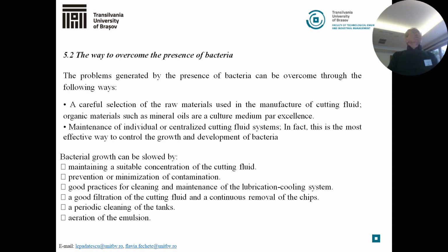Bacteria growth can be slowed by maintaining a suitable concentration of the cutting fluid, prevention or minimization of contamination, good practices for cleaning and maintenance of the lubrication cooling system, a good filtration of the cutting fluid and a continuous removal of the chips, a periodic cleaning of the tanks and aeration of the emulsion.